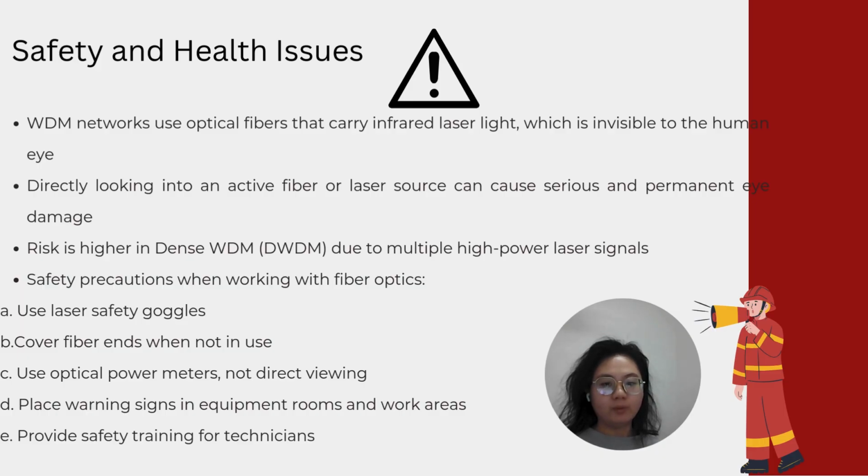To stay safe when working with fiber optics, technicians must wear laser safety goggles, keep the fiber ends covered when not in use, and use an optical power meter instead of direct viewing. Warning signs should be placed in equipment rooms and work areas, and proper safety training must be provided to all technicians.